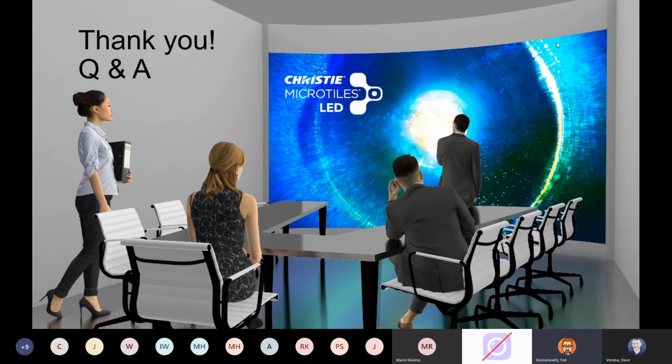So you just hot swap the module boards. Again, they auto match to the wall. You take the damaged module board and ship it back to a Christie repair facility that's closest to you. At that time, we pull your reel, repair the pixels and return them very quickly, usually in a week or less. The old one comes back, and you can either replace it on the wall, or more likely put it back up on the shelf and use it if you need to down the road.